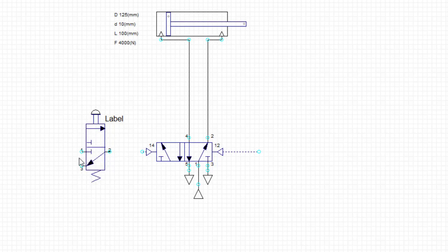Okay, so I'm going to hook up the connections from this push button into the valve. And first I have to supply compressed air to this port, the one that's teed off. What I'm going to do is take this compressed air, move it down a little bit. I have to redraw this line so it's longer. And then I'm going to draw a line from the compressed air source over here to this port. So you notice this valve, in its normal position, does not allow the air to flow in, so it won't provide any air to that pilot port. I'm going to draw a connection here.